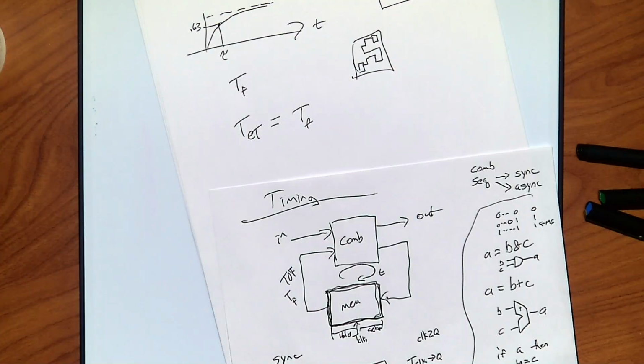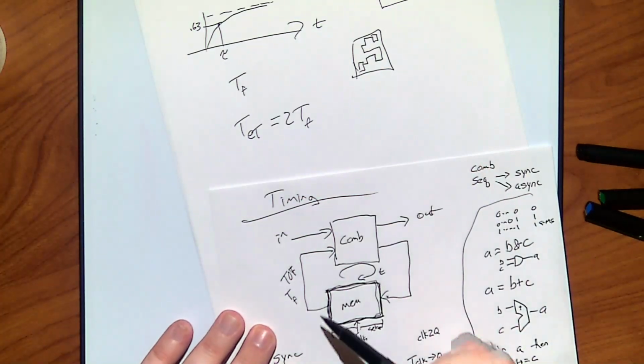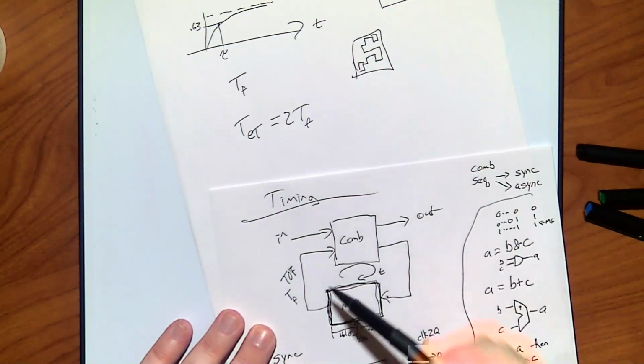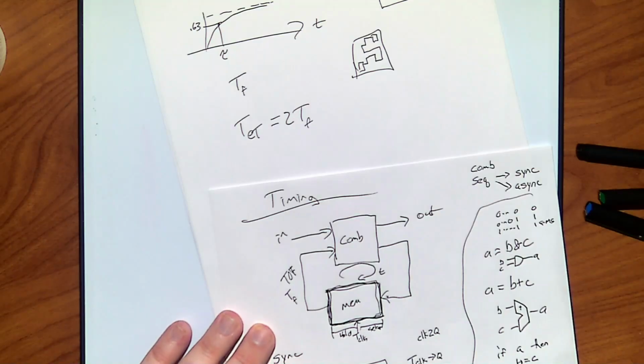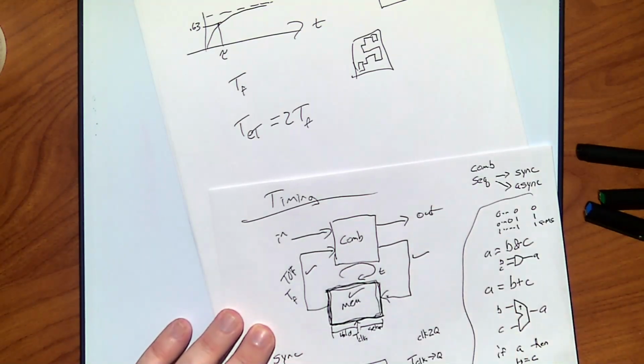So usually once you have calculated the logic, the flip-flop is right after it, so there's appreciably no link because they're in the same little memory cell. There are some cases if you go to an external RAM where it could be there. So often it's either time of flight or two times time of flight. If this one's really short, we ignore it. That takes care of this, and we've talked about mostly memory.